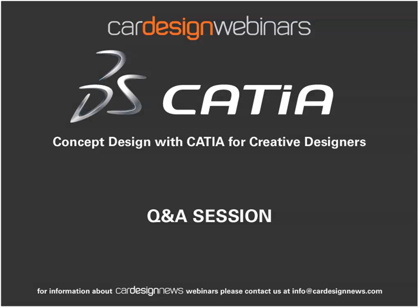So with KnowledgeWare, you can have dedicated people in your company who can create this kind of automated rules-based object creation. For the SU, we use this KnowledgeWare, which automatically, based on a curve, will generate geometry, and you can choose what you want. Here we chose a surfacing model, a subdiv or a NURBS model. It was a NURBS model, which was automatically generated based on a curve. The user has just to select the curve, and then the SU will follow the curve.